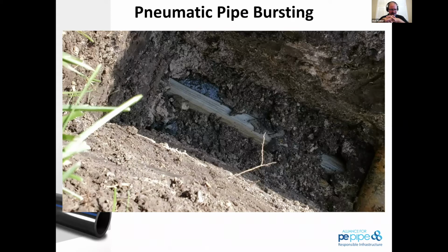That impact hammer just inches its way through it. In sensitive areas, you might want to give consideration to noise. Static pipe bursting doesn't make as much noise through that impact process. There still is noise associated with inserting the rods and pushing it through, but that video simply was there to illustrate that inching along of the impact hammer as it is continuous.